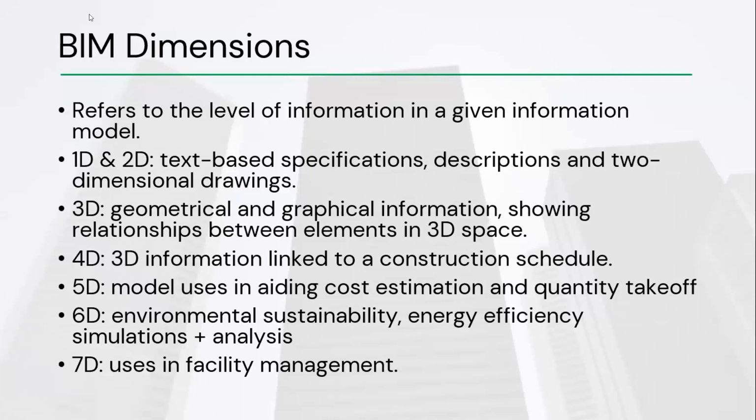When we talk about 4D now, the three-dimensional geometrical and graphical model is linked to a construction schedule. See how we develop construction schedules using Microsoft Project or any other software. That can be imported to a 4D BIM software like Synchro or Navisworks. And then the model elements are linked to it.